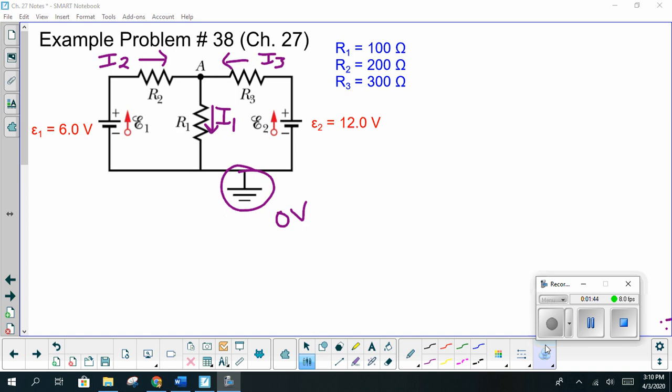However, if you find yourself on a problem in the homework that you're not sure which way the charge flow is going to move or what direction the current is going to go, don't worry, just assign it a direction. So literally on the diagram, draw the direction that you think the current is going. If you end up with that, let's say you identified it wrong, that's okay. What will end up happening is when you solve the problem, you'll get a negative value for your current. No worries, no big deal. You just know that you assigned it the wrong direction. What's so important, though, is that you assign each current a direction through each resistor, and you stick with that direction consistently throughout the whole problem.